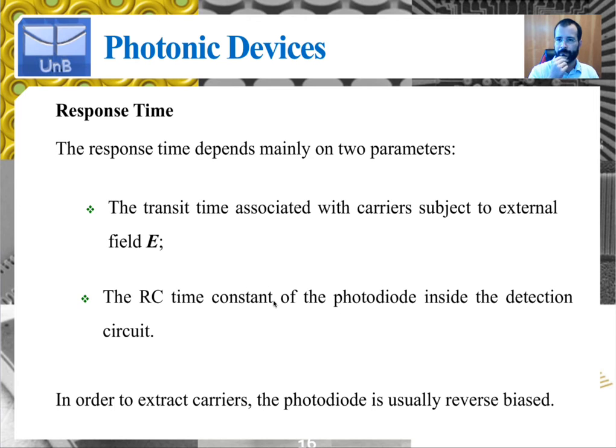So the photodiode is going to be inside a circuit which has a certain equivalent resistance. Therefore you'll have basically a series RC circuit which is going to have an RC time constant. So the maximum speed with which the voltage across the load of this circuit can respond depends on this RC time constant, as we would expect.